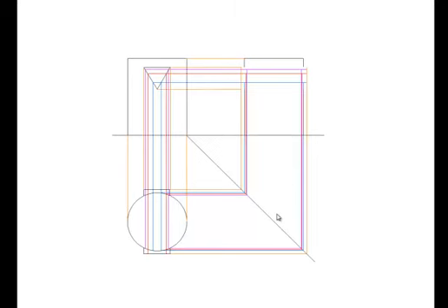These piercing points can be joined together to create the line of intersection. Note, as said before, as we are dealing with a curved surface, as you can see, this is a cylinder, this is not going to be a straight line of intersection. So, thanks to the elevation and the plan, we can now locate the position of the prism in the end view. It is here and here.